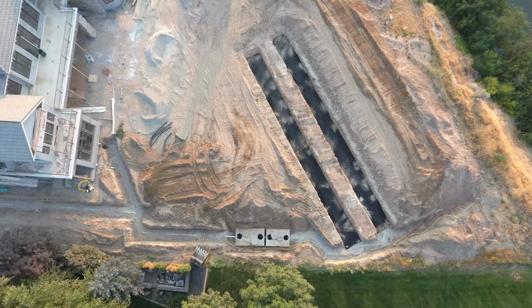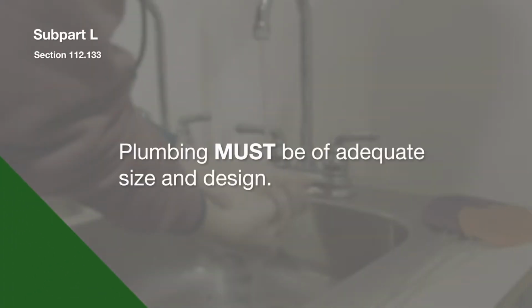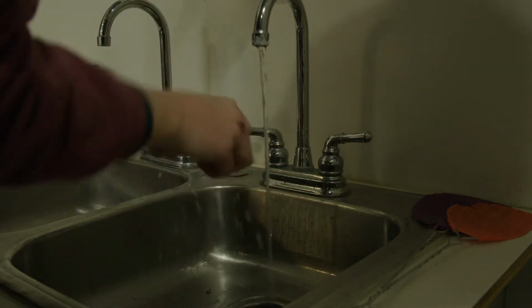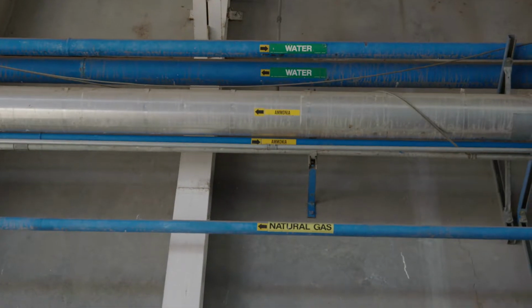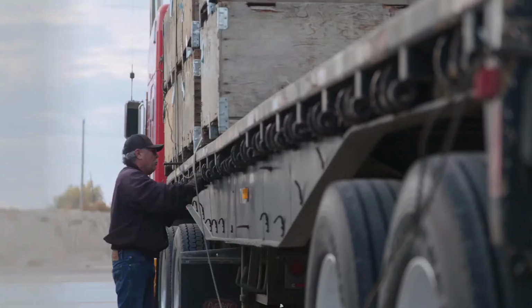Sewage and septic systems need to be adequate and maintained in a manner that prevents them from becoming a source of contamination. The plumbing must be of adequate size and design and be adequately installed and maintained to distribute water under pressures as needed, in sufficient quantities, in all areas used for covered activities, for sanitary operations, or for hand washing and toilet facilities. It must properly convey sewage and liquid disposable waste, avoid being a source of contamination to covered produce, food contact surfaces, areas used for a covered activity, or agricultural water sources, and not allow backflow from or cross-connection between piping systems that discharge wastewater or sewage and piping systems that carry water used for a covered activity, for sanitary operations, or for use in hand washing facilities.